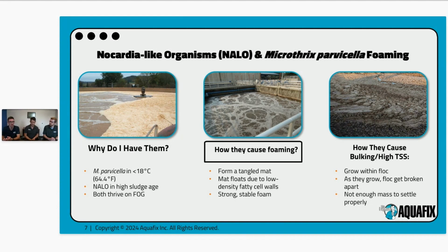That's never going to go away unless you do take action, especially if you don't control your fats and greases. That issue will continue to persist. That foaming will get worse. So you're going to start getting clogging of any sort of instrumentation. DO probes might get bound. You're going to get inaccurate readings. A whole host of issues when dealing with this issue, and with no action, they're always going to continue to get worse.